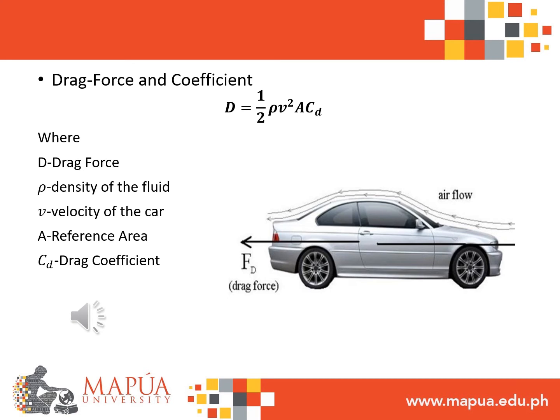In determining the drag force, there are many factors that need to be considered, such as shape, inclination, and flow conditions. For simplicity, these complex factors are characterized in one variable called the drag coefficient. The drag coefficient can be expressed as the ratio of the drag force to the force produced by multiplying the dynamic pressure and area. In comparison with the lift coefficient, determining the drag coefficient is more complicated because there are more sources of drag, such as form, induced, wave, and ram drag.